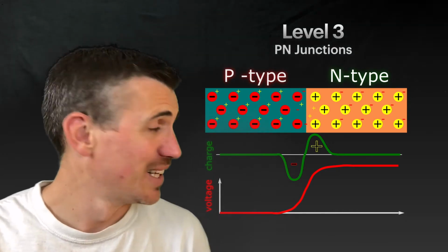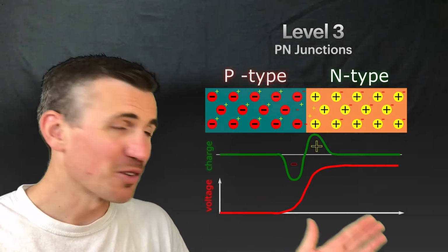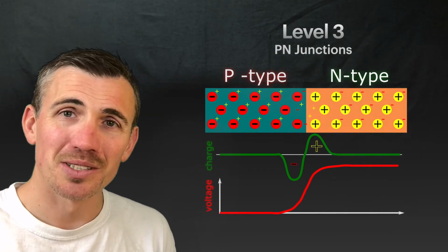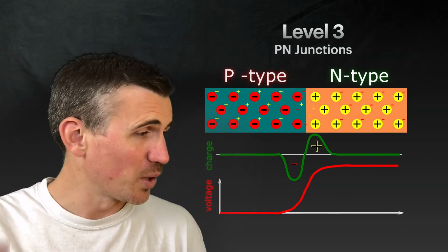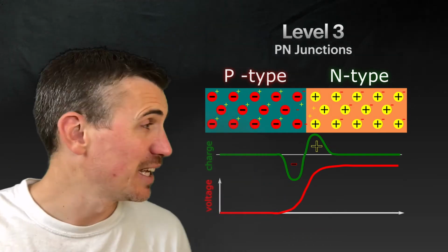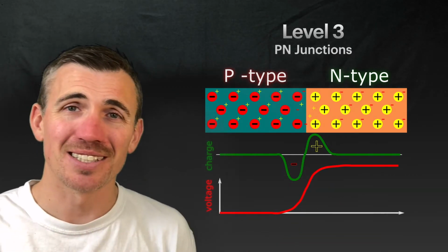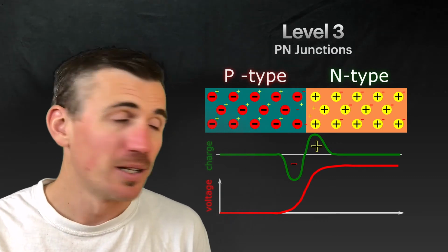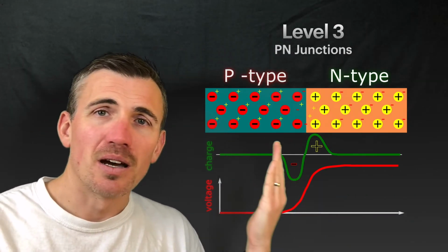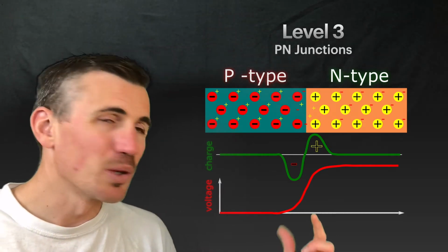But this is very cool, because if we have a charge distribution, that means we have an electric field. And if we have an electric field, we have a potential difference. We have an energy per unit charge. So we've actually just made a voltage source, not by making a battery, but literally by taking one type of doped silicon with another type, banging it together. That's it. That's our junction. It creates a voltage source. It's tempting to think there's a battery in here. There's a potential barrier in this thing, right? And there are two processes going on, remember. There's the diffusion, just from the thermal agitation, and the drift of the charges that are being pushed by this distribution. And in equilibrium, they balance out.